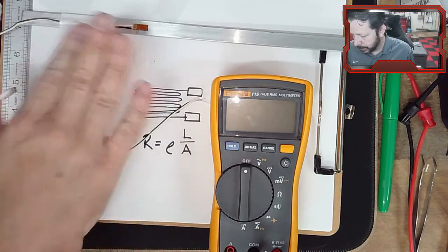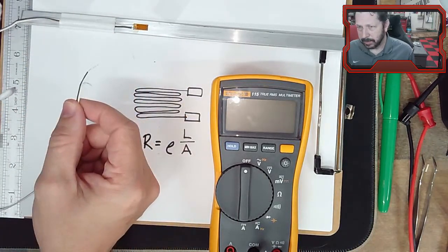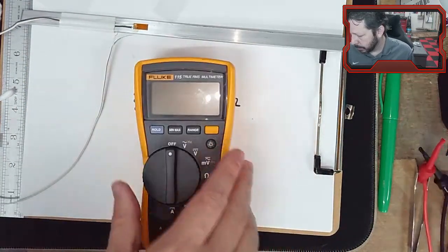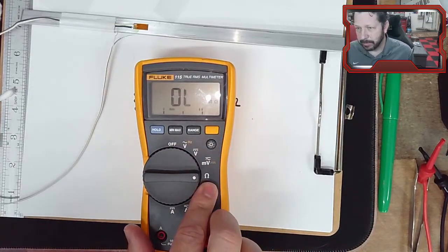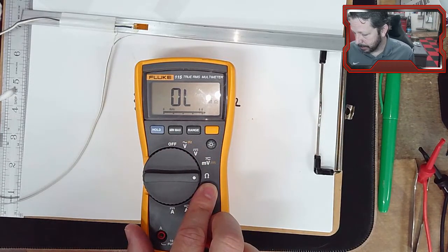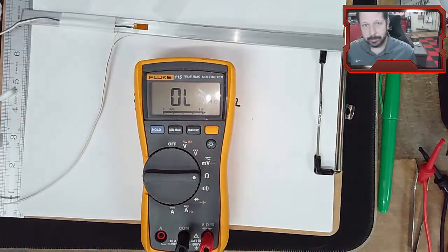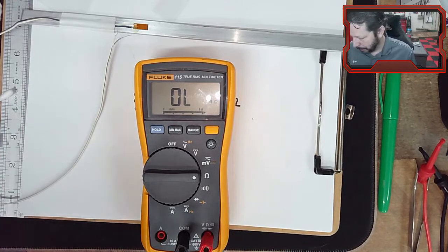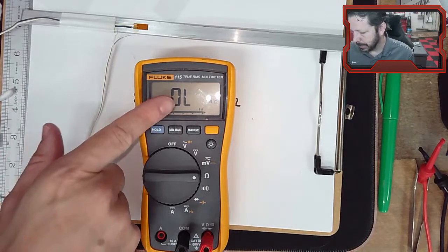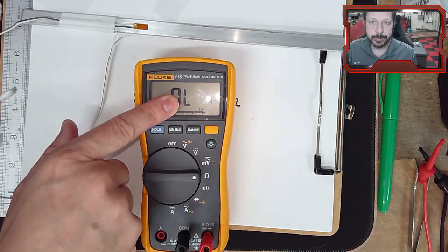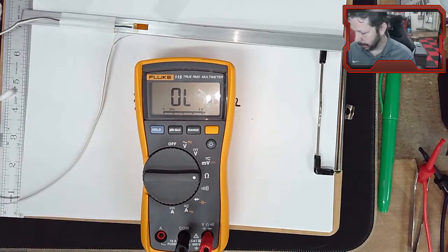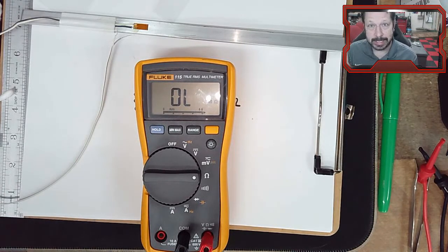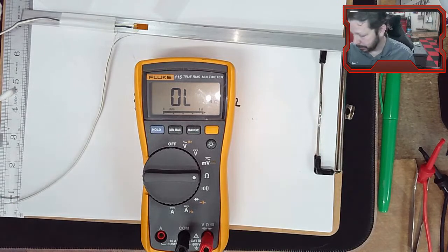That's what you want. Once you get it mounted and everything, hook it up to your multimeter, switch over to reading resistance, and you should be able to flex the beam. It is aluminum, so don't flex it to the point of yielding it, but flex it enough and you should be able to see the tenths spot move on your multimeter, go up a couple of tenths of an ohm or down a couple of tenths of an ohm. All right, so work on that.